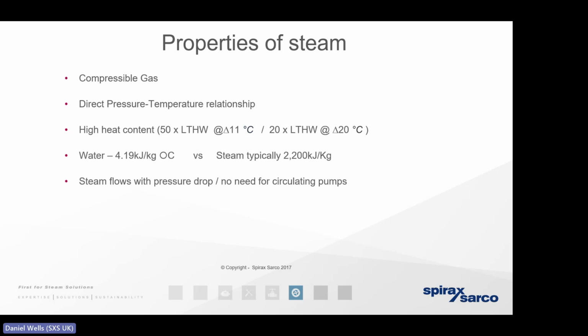Again, steam's a gas. It moves in accordance with the pressure drop. So if we've got a steam boiler that's operating at 10 bar gauge pressure, if we're using the steam at the heat exchanger at a much lower pressure, thousands of meters away, well, it tells us that the steam's going to move all by itself. In other words, we don't need to pump it, as we would do with an alternative source of energy.